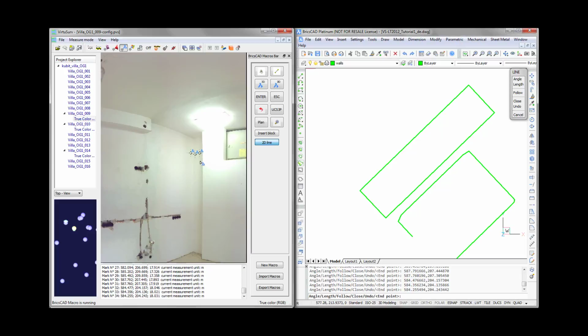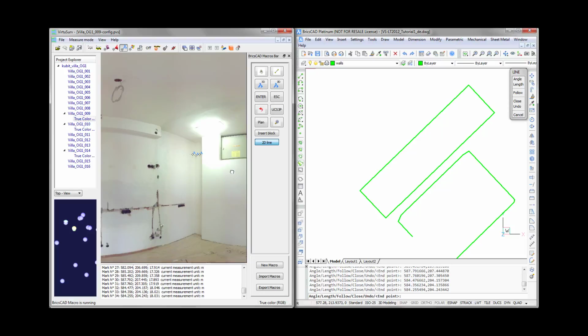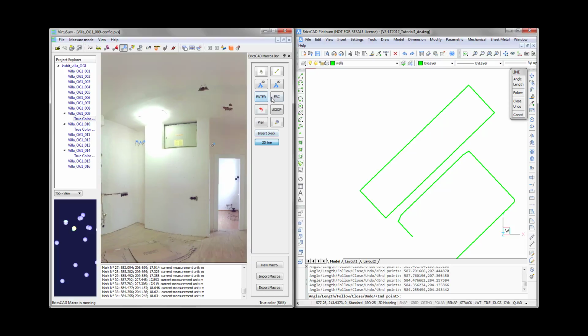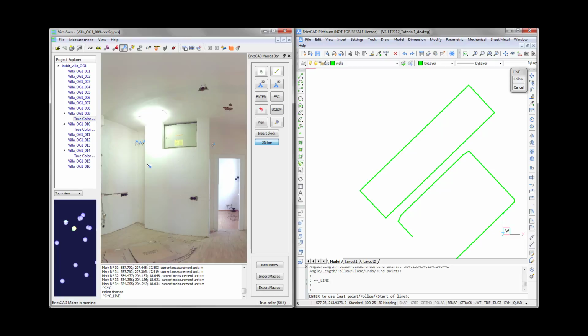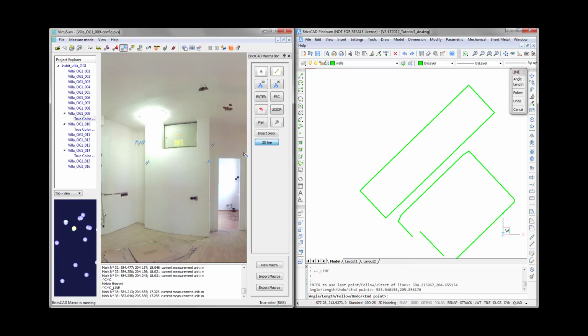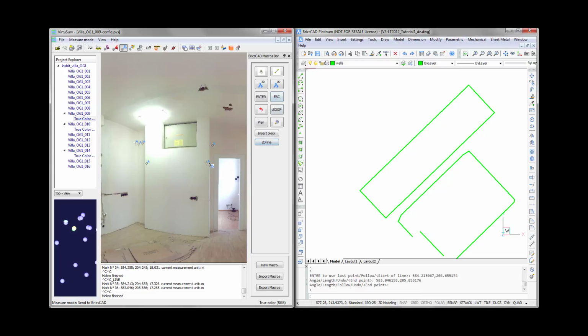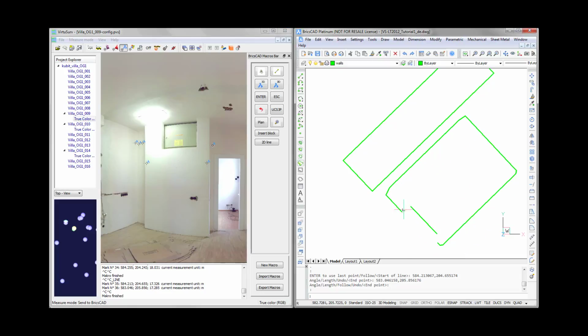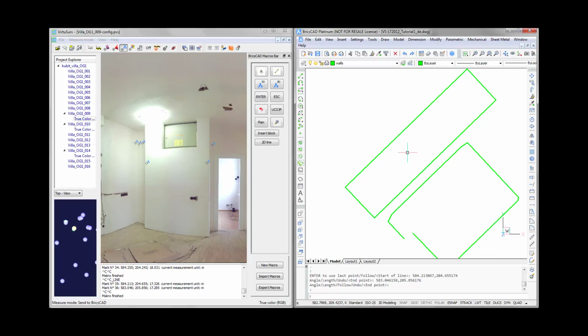I will not finish with a right click right now because I don't want the polygon to be closed, so I hit escape in VirtuSurv, and I will start just this command again to get 2 points on these walls, and the rest, if I don't have scan data, and at the moment I don't, I will have to close these gaps manually by construction. And again, I could fix these corners nicely by the same principle as shown on the first room.